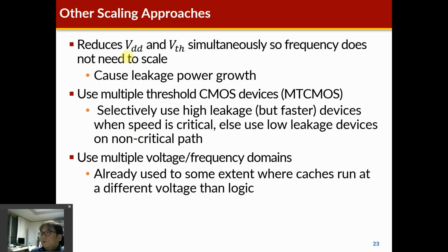So actually VDD and VTH can be scaled simultaneously. The frequency does not need to scale, but leakage matters. So VTH, this threshold voltage, is critical for static power, the leakage current. So we can apply multiple threshold CMOS devices. It's called MT CMOS.